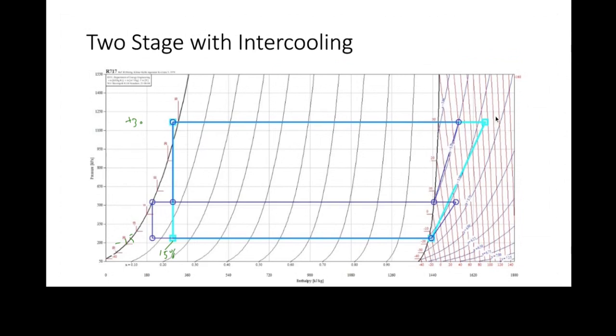And then we compressed it. We achieved a really high temperature. I think it was like 110 degrees Celsius, something like that. Okay. And so we had adiabatic compression, which is problematic for us in terms of its energy consumption. And because we had lots of flash gas, we had a small net refrigerating effect. That was our NRE. So, you know, smaller NRE.